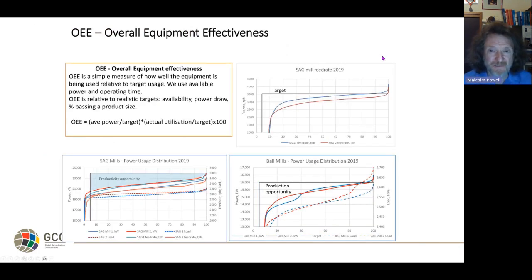And OEE that Magnus brought to my attention, you look at basic cumulative distribution and where you are below where you'd like to be. It's a nice way graphically of illustrating, and it gives you a single number. My OEE is 72% and it should be 96. That's not too good. OEE is 96 and I'm expecting 96. That's cool. Look somewhere else. So these help guide you to where the issues are on site.